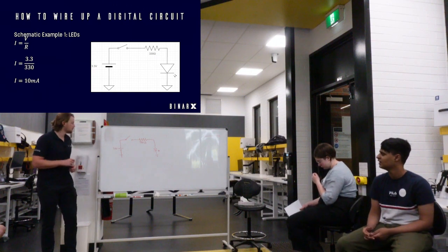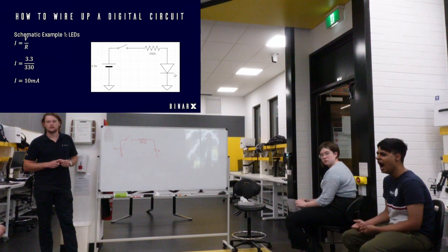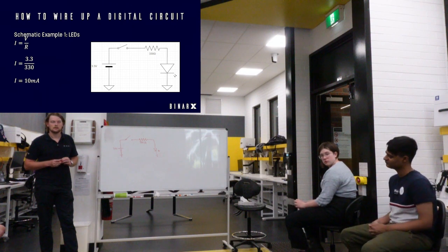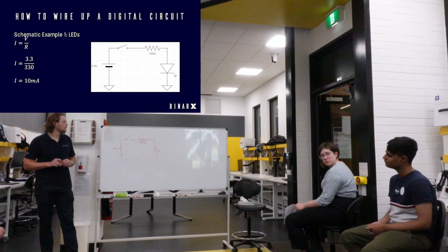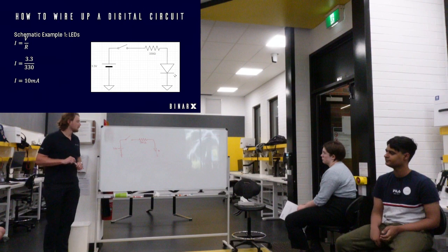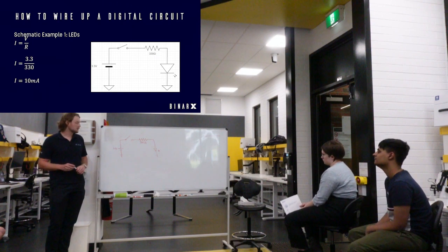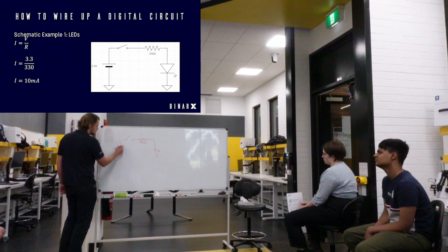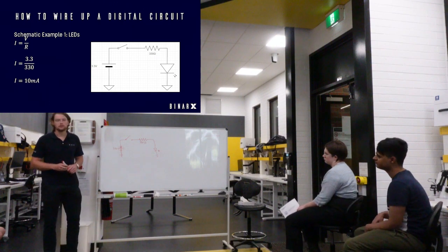They had the TTL levels, which were 5 volts, and then when CMOS processors came out, that's when they started using 3.3 volts. Now a bunch of chips also work at 1.8 volts, but 3.3 seems to be happy. Which is kind of inconvenient because it doesn't perfectly line up to any batteries normally. So typically you represent this as more of a source like this, but a battery works the same in the case of what we're doing here.